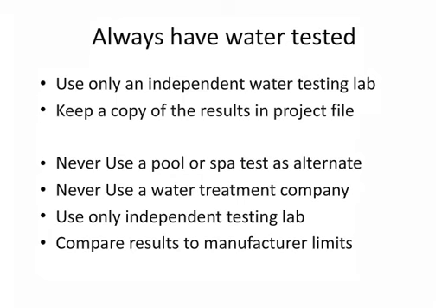And by the way, if there is any kind of a rotten egg smell, that is hydrogen sulfide. You want to make sure that you get that water sample to that testing lab right away on that same day, not an overnight thing. Make sure you have a lid that's sealed tight, and when you bring it in and fill out the paperwork, let them know you suspect hydrogen sulfide and you would like it tested right away, because hydrogen sulfide is a gas that will outgas and dissipate, and it will be difficult for them to test for that level. That is a critical thing you need to be aware of if it exists at all.